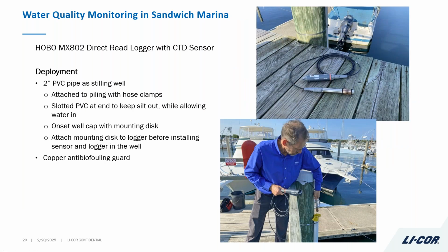So here's the deployment, actually closer to home. That's me, deploying the MX802 direct read loggers with a CTD sensor. You can see it here on the dock, and you can see the cable here. I forget which length I used. The water change is about 10 feet. I think I used our 4-meter or 5-meter cable for this, because the dock's pretty high up.